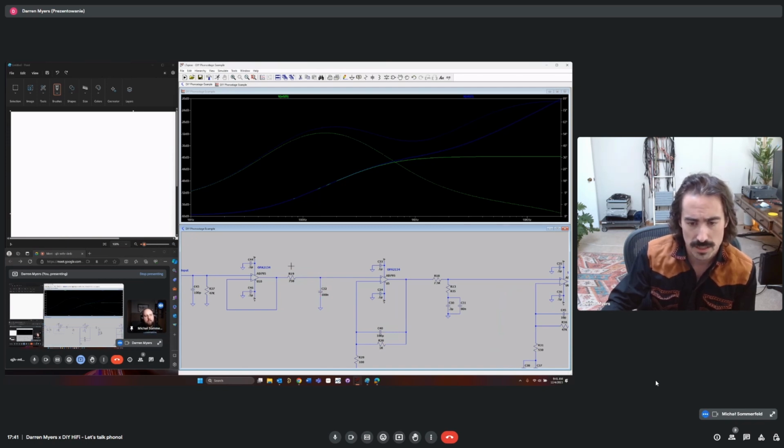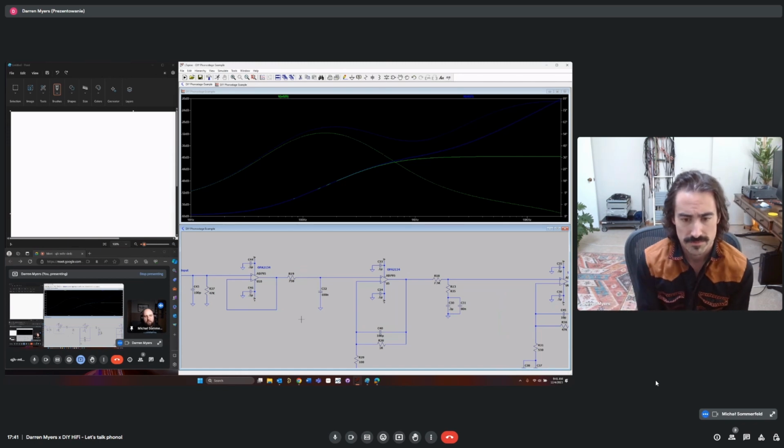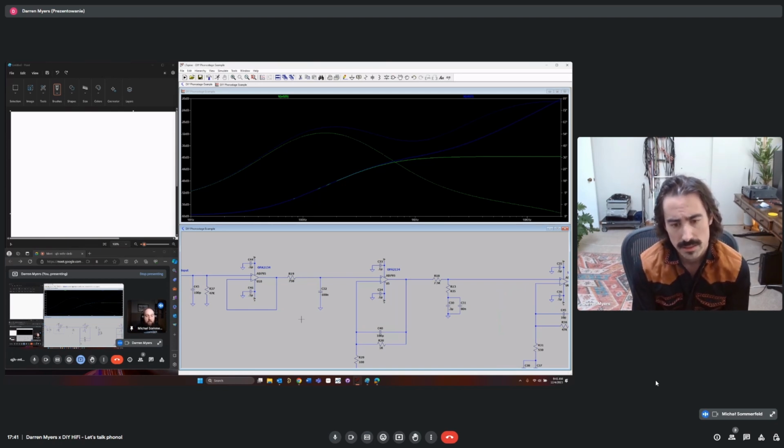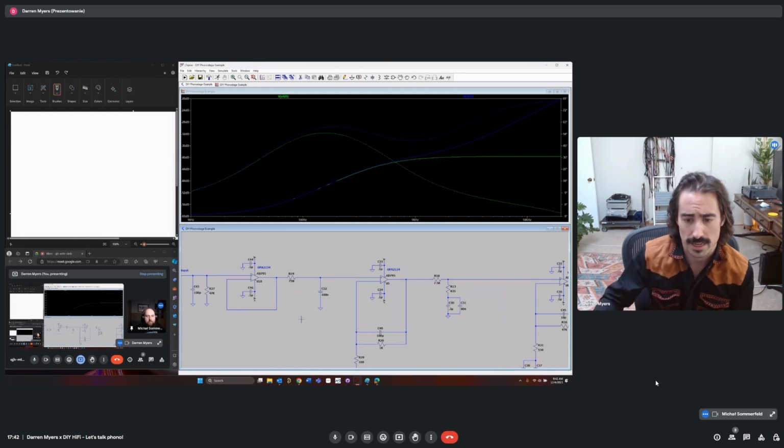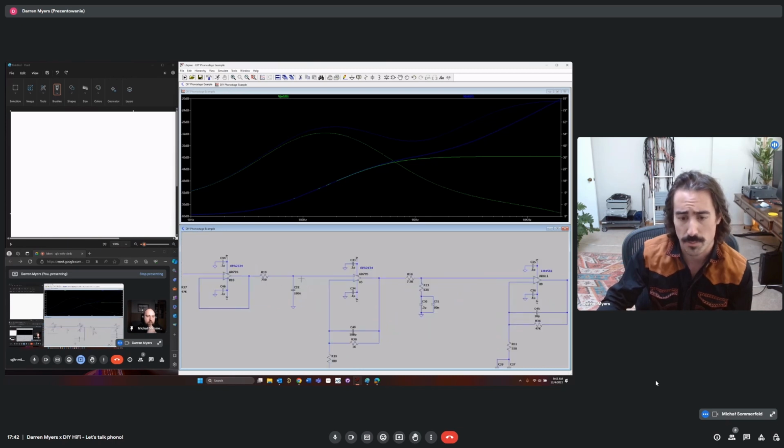Yeah, exactly. So not every op-amp can drive 300 ohms. We have to remember that. Most of them are good at driving 600 ohms, the old standard. But not any op-amp can do 300, so you would have to check beforehand. Exactly. So this is why I picked 750 for this example. I've applied the